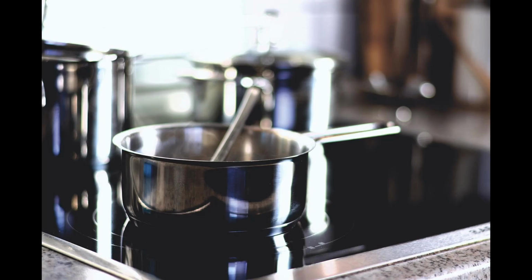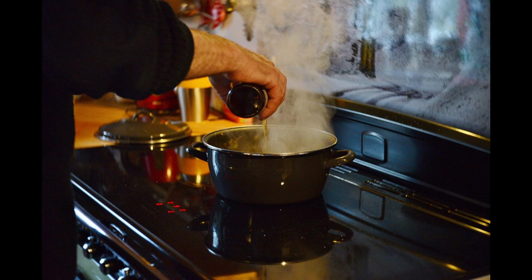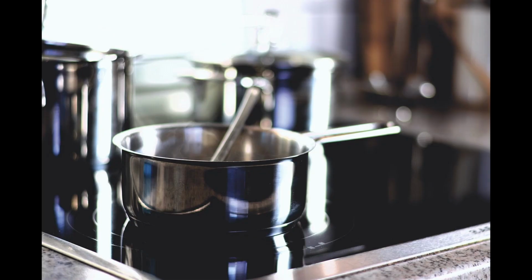A practical application of inductance can be found in inductive stoves. Here, the stovetop utilizes a conductive coil below its surface. An oscillating current is passed through the coil. This changing current produces a changing magnetic field. If there's conductive metal on the stovetop, like from a pan, those changing magnetic fields generate eddy currents within the pan, which also produces heat. The continuous application of this energy to the pan causes the pan to continue to heat up, even if the stovetop itself doesn't get hot.